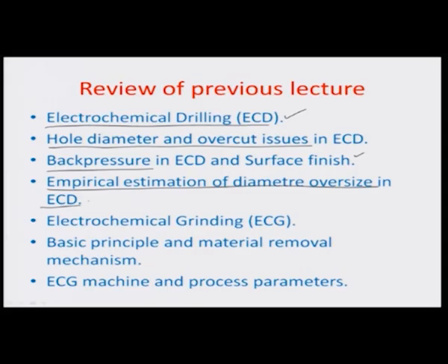Finally, we did the other associated process, electrochemical grinding, where most of the material, about 90% or so, was found to be removed by electrochemical dissolution, and about 10% of the material would get removed by physical ablation. One of the reasons why ECG wheels always have higher life, and the process is an advantage over mechanical abrasion, is that there is a self-smoothing effect because of the electrochemistry involved in dissolving whatever layers are ablated from the surface.